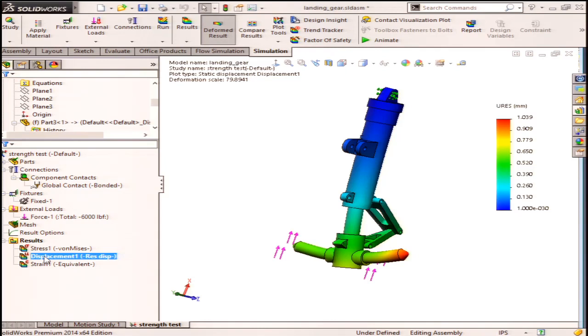Ever hear of stress concentrations? It could be what we call a singularity point. Stress is basically force over the area. If you keep taking smaller and smaller measurements, you're changing the size of the area, making it smaller and smaller. And as the area approaches 0, your answer just keeps getting larger and basically goes to infinity.